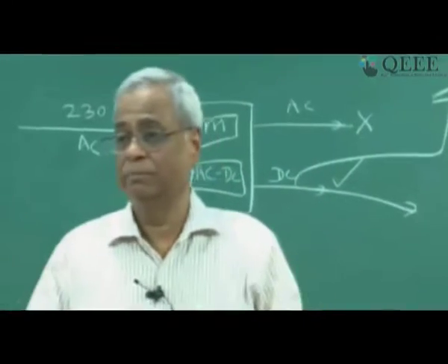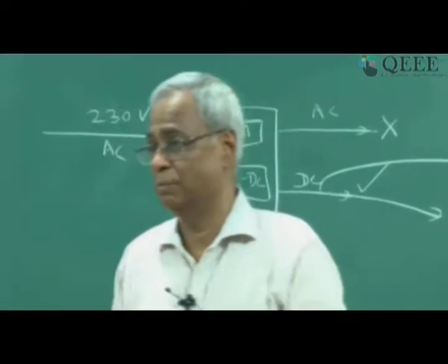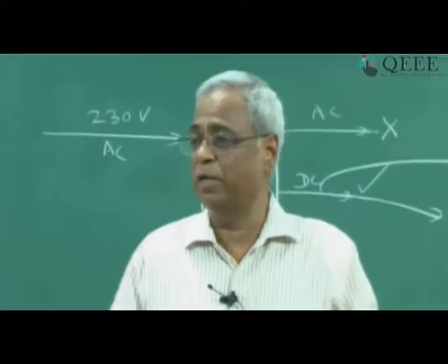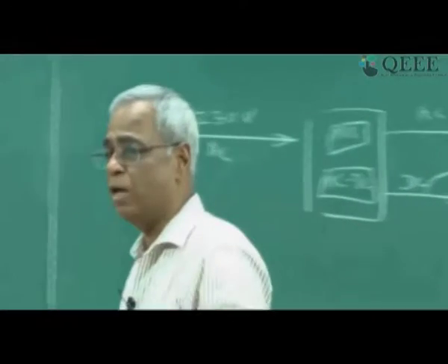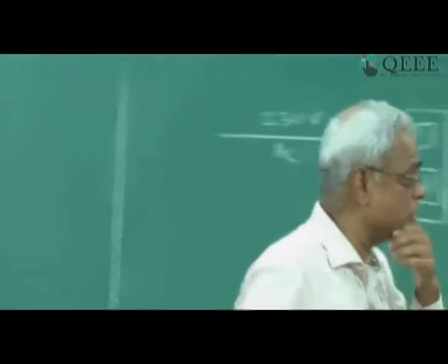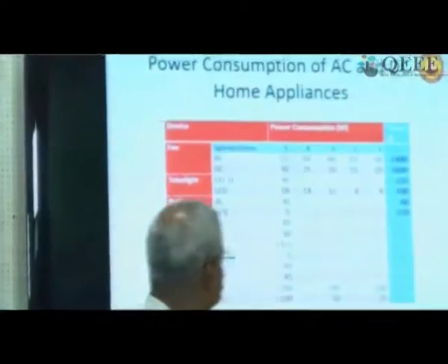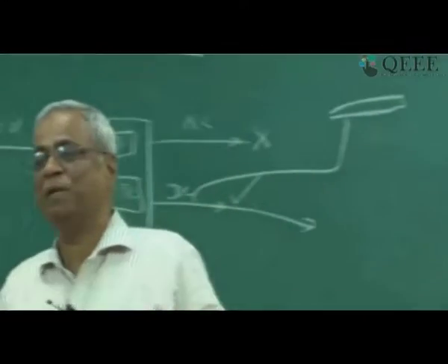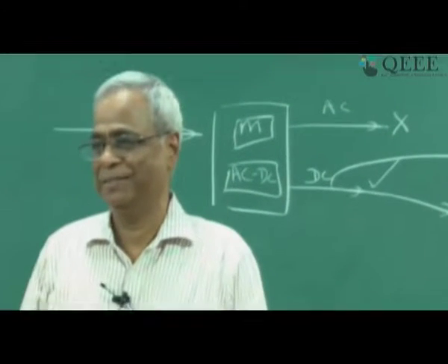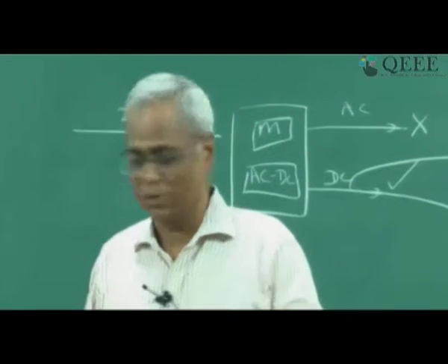Air cooler, the desert cooler, what we call. In dry climate only it can be used, cannot be used in Chennai. Small one, 250 watts, we have taken 100 watts. And here also we can change speed, 250 watts can become 230, 210, and here 150 and 25. So again in AC, if you reduce speed, it doesn't reduce power too much. In DC, it significantly reduces power.